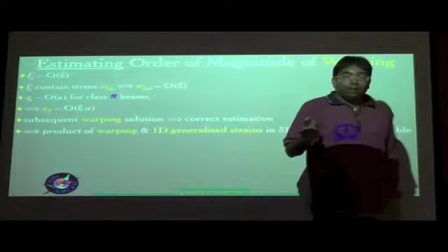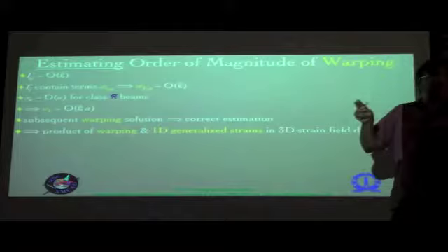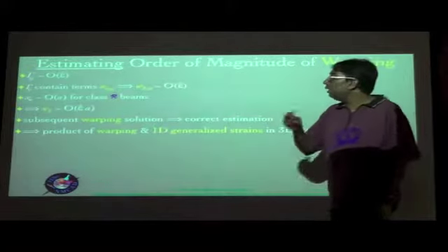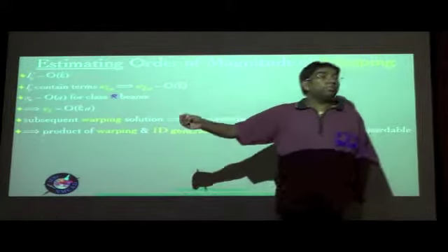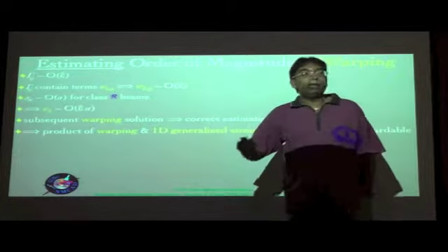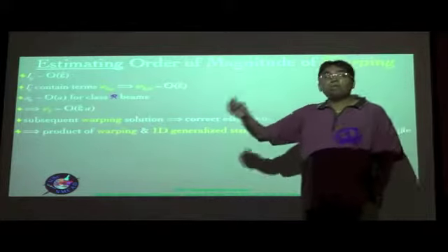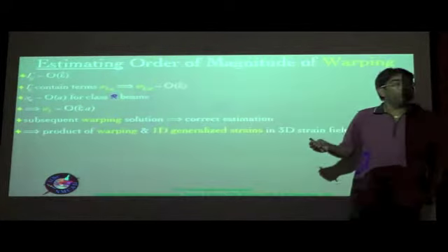That said and done, in the variational asymptotic method, the right place to do the dropping off of higher order terms is not the strain but the strain energy, or rather more specifically the total potential. So that's where the dropping off of the higher order terms should happen.